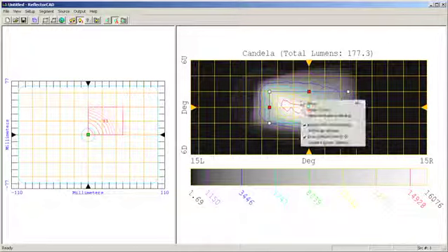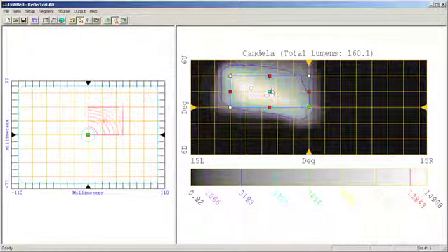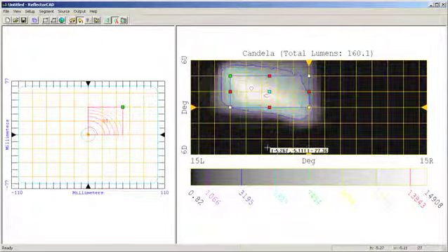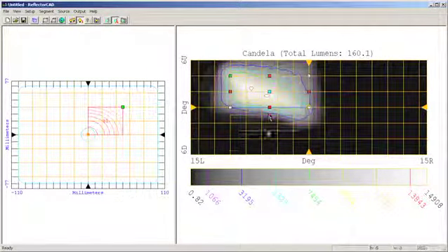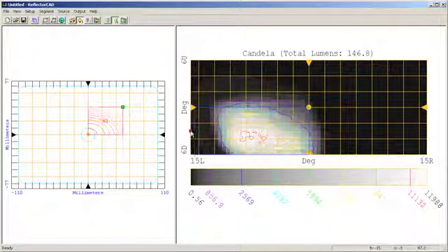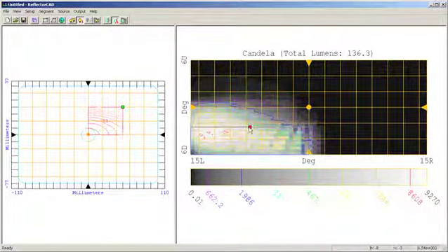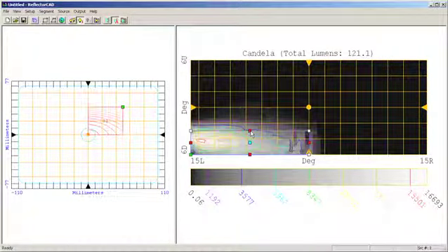In fact, what I will do is actually operate on the luminous intensity pattern, changing that pattern to the desired shape that I want from that particular segment by dropping and dragging the various areas around the luminous intensity pattern, and ReflectorCAD will automatically update the shape of the segment in order to produce that particular luminous intensity pattern.